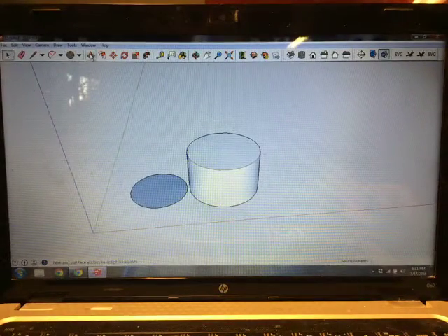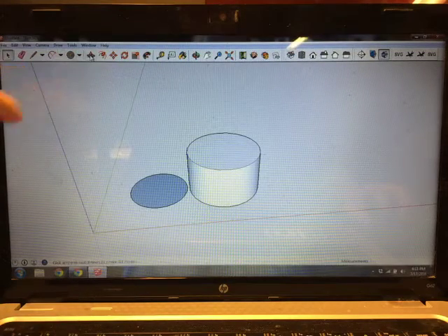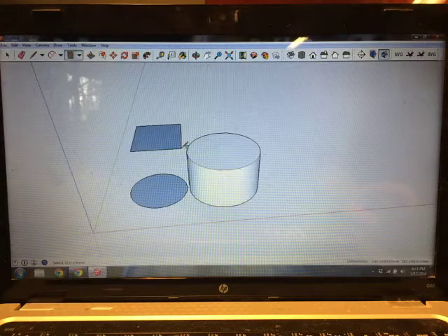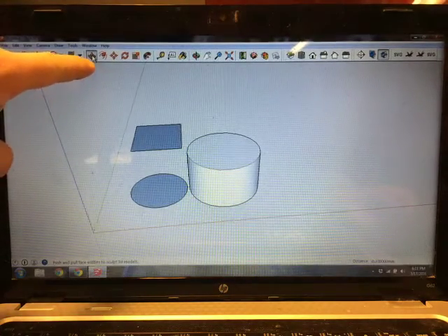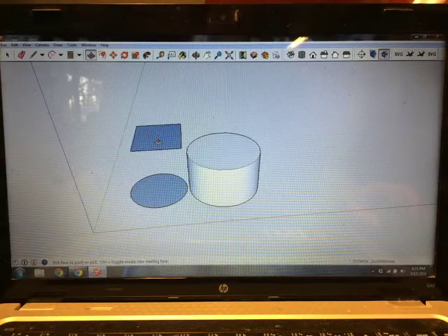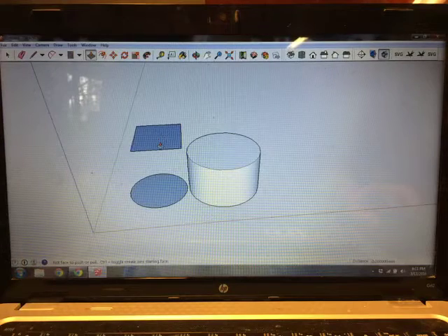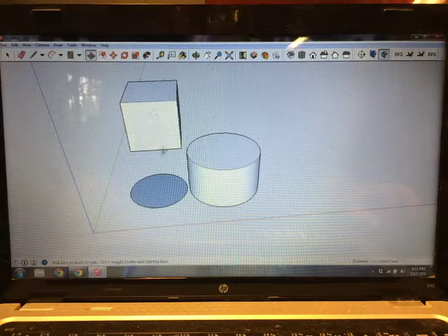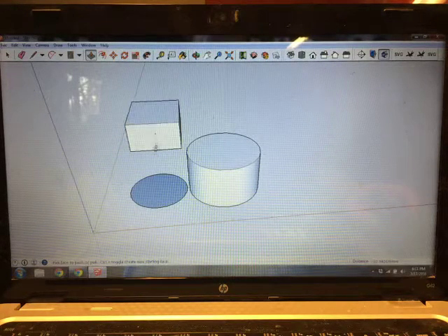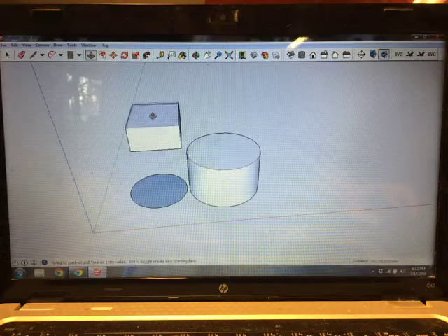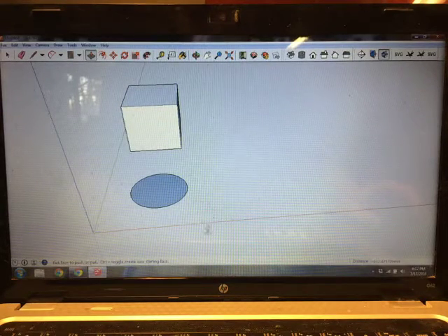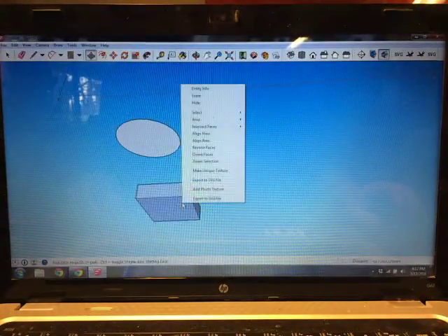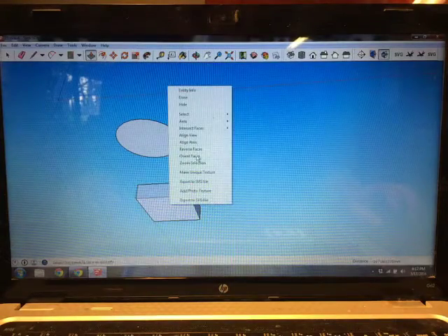Okay, so you may have just noticed this push-pull tool. You can create circles, and you can drop that down and create rectangles, a single click and then a single click. This is the push-pull, or some might call it extrude. You'll notice the face turns a little hash-marked or dotted. You can click once and drag up. Sometimes in this program, if you click and move quick, it'll deselect it. So click and then move. See how it deselected it? Oh, that one disappeared. And then, boom, I went all the way through it. So there are some issues, and then reorient the faces on that one.